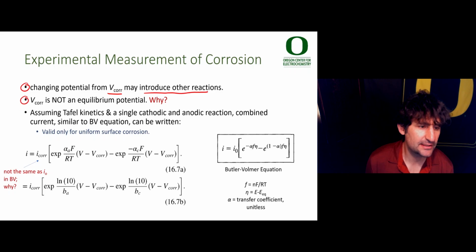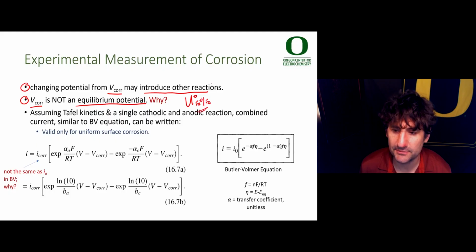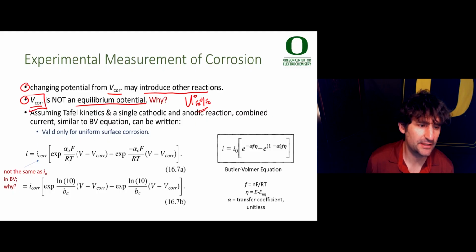I also emphasize that V corrosion is not an equilibrium potential. It's not like U naught for Fe2+/Fe, for example, which is a defined thermodynamic quantity. V corrosion depends on the kinetics of the reaction. It's a steady state mixed potential.